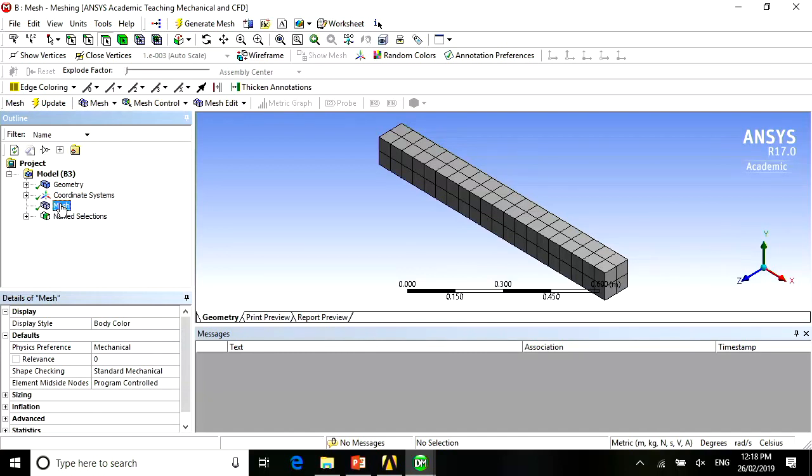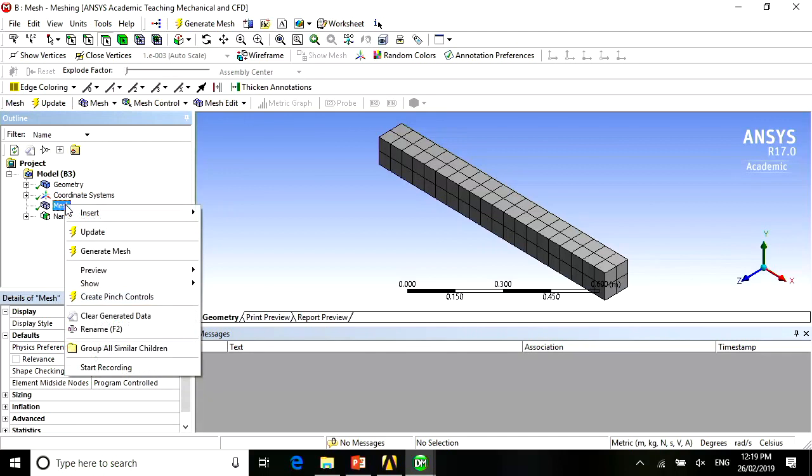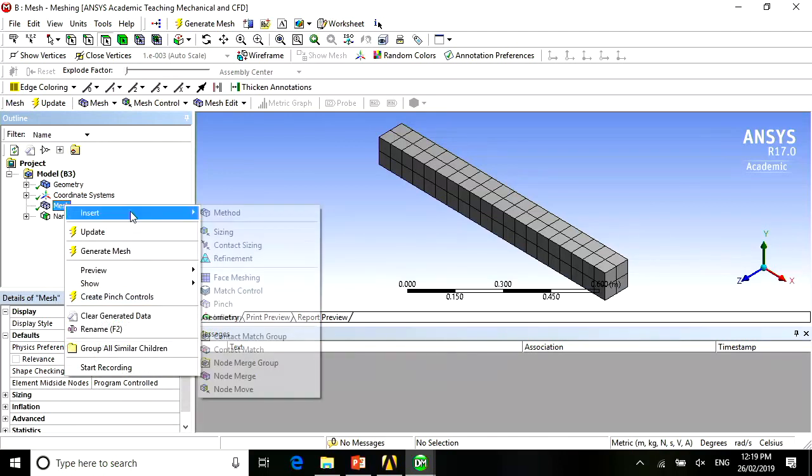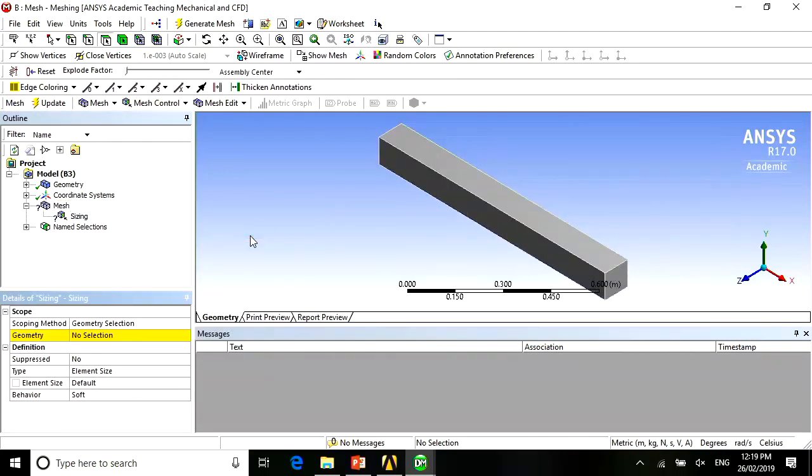So CFD is about meshing. That's why I re-emphasize it's all about meshing. And it's about mesh resolution as well. Now, what I'm going to teach you here is how you can regenerate the mesh using the divisions of elements that you require. So the one option here is that you click on your right-hand things. You got Insert, Sizing, right?